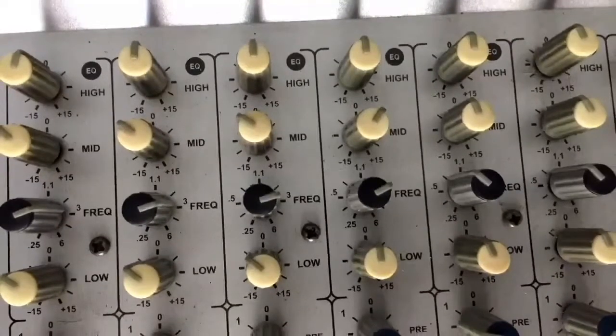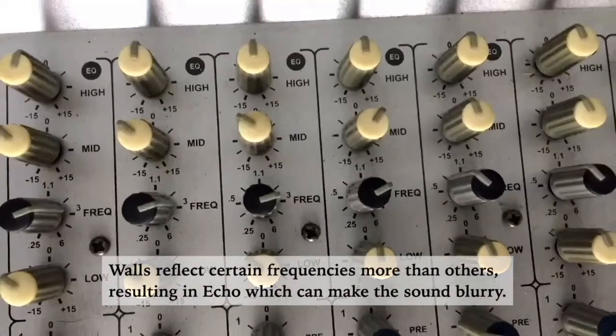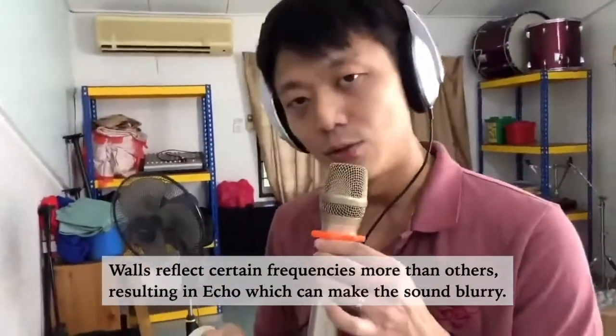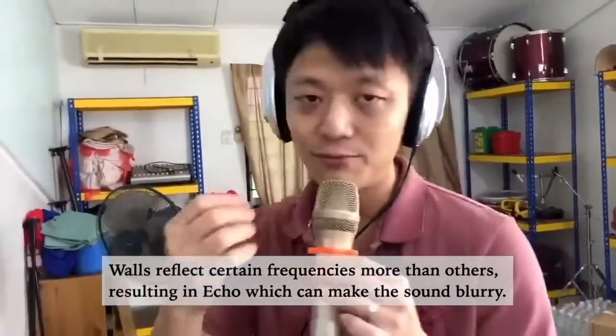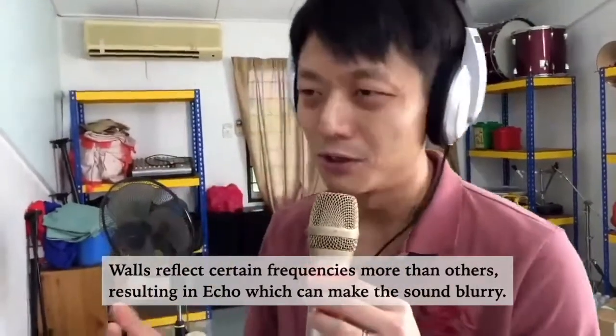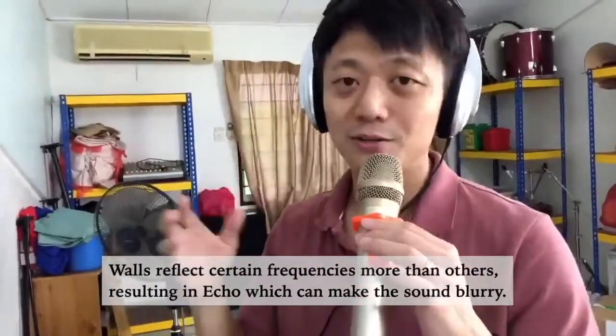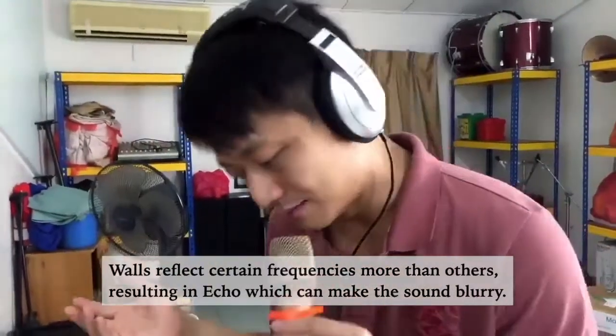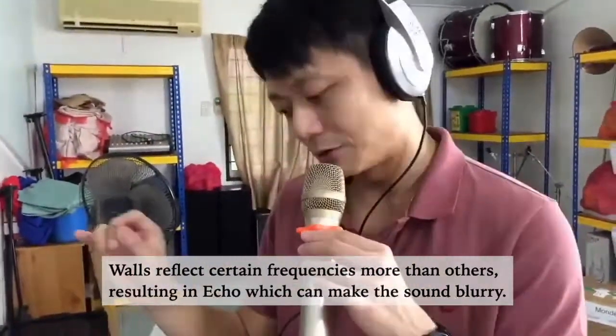Okay, because the hall surfaces, the walls, reflect different frequencies differently. So what I noticed in our hall is that the middle frequency gives you a lot of echo. So I don't want too much of that echo. So I'm going to cut the middle frequency by a bit, maybe about 5 decibels. And then I choose about 3000 Hertz.